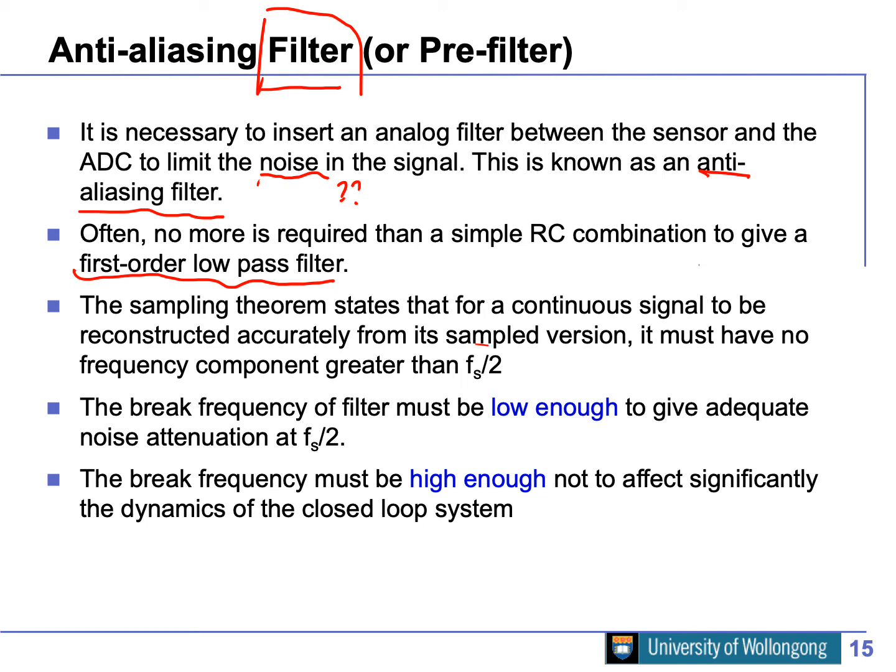And the bandwidth of this filter will be half of your sampling frequency. So if we do the sampling, this is our omega s, negative omega s, make sure there's no signal outside. So you get a curve within, and the next curve is within, so it doesn't get aliased back onto the original signal. So that's the minimum we choose for the anti-alias filter.